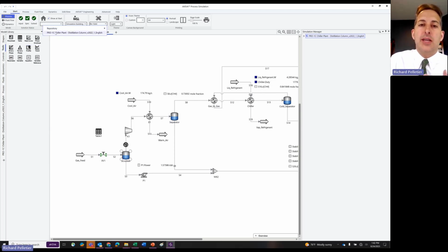But I can also create slates that are specific to the simulation file. I don't have any created here, but if I did, I would have options that I can pick from here where the unit of measure slate is stored with the file. Meaning if I exported to a SimX, just like the information in my simulation model library, the unit of measure slate in my simulation file will be stored in the generated SimX file.